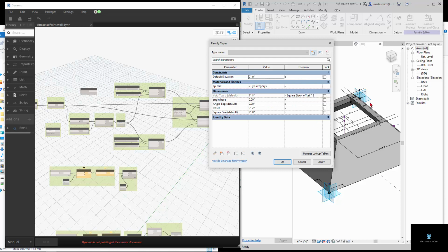The main thing that happens when we bring it into Dynamo with this void in it is if that gets down to 0, past 0, it will fold in on itself and self-intersect, and it can't create the form. So we have to keep that void at least 2 times the offset, right? So it doesn't start to fold in on itself. And we'll see how that works.